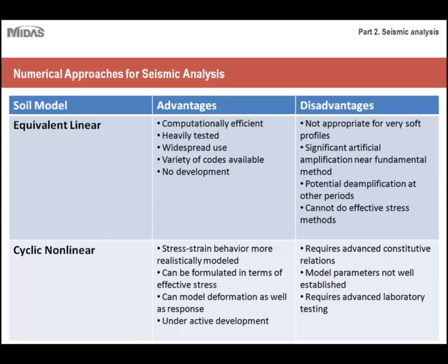And then also it requires advanced laboratory testing. So for example, if you were to do a seismic analysis for a certain site, you might have to run your own laboratory tests, or you might have to sublet that work to someone else in order to get these constitutive models that you would need to perform your cyclic nonlinear analysis.